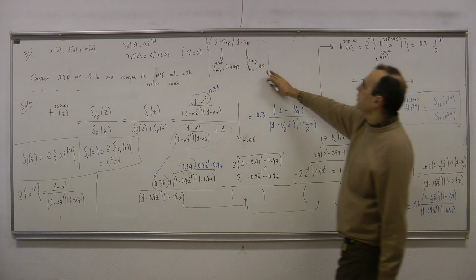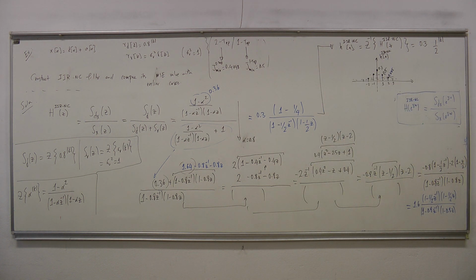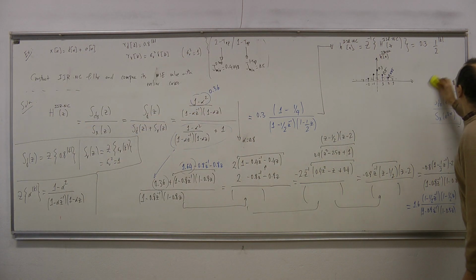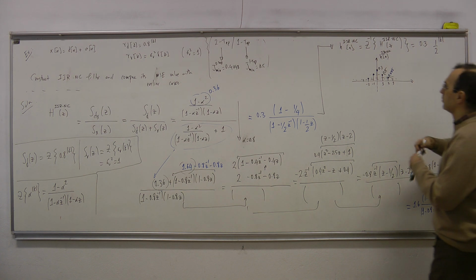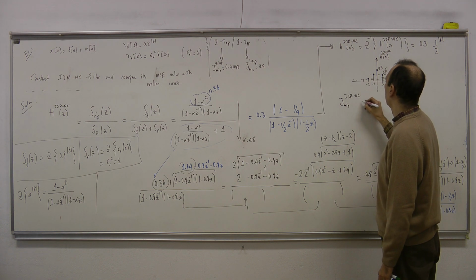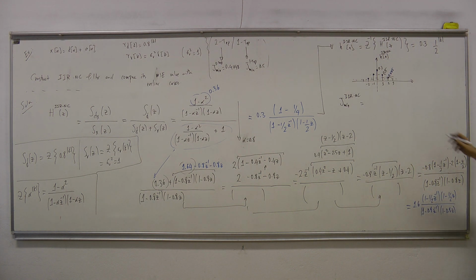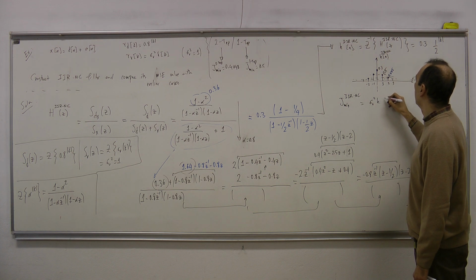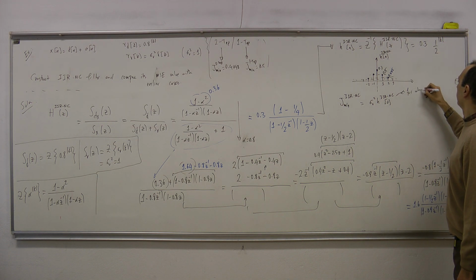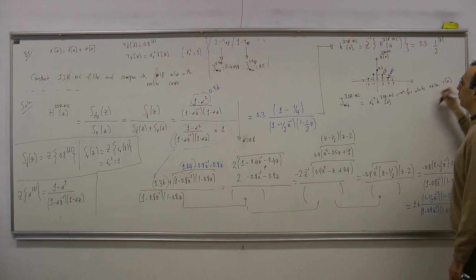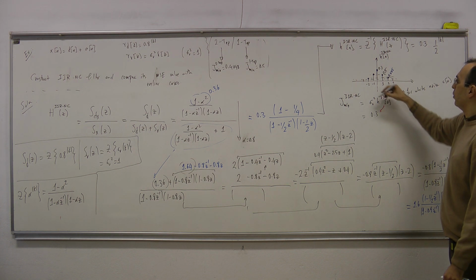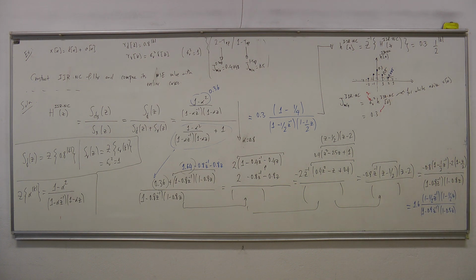Now the question is, what is the minimum error for this one? Well, we had a result. Maybe we can derive that result, but so J minimum IIR non-causal is, so what was this? We have derived the result. It was sigma v squared times h IIR non-causal 0. But remember that this is for white noise only, for white noise v of n. So this is equal to 0.3, because h0 is 0.3 and sigma v squared is equal to 1. Okay. So is this correct?